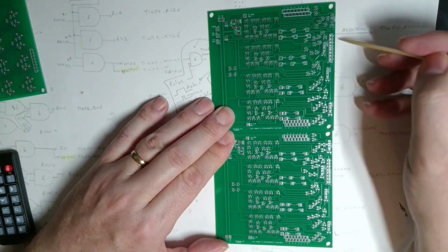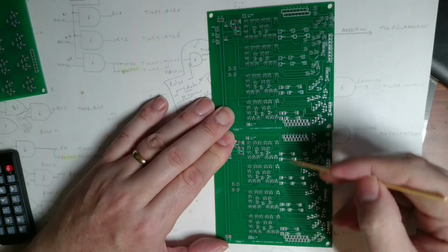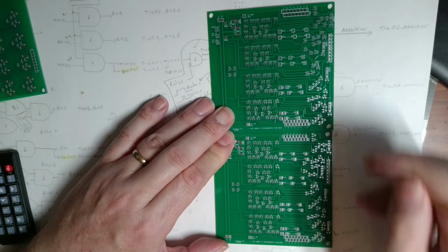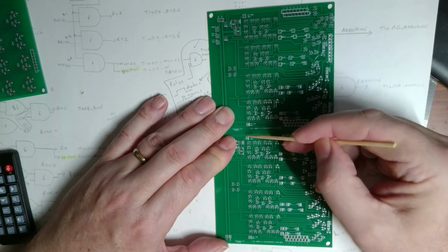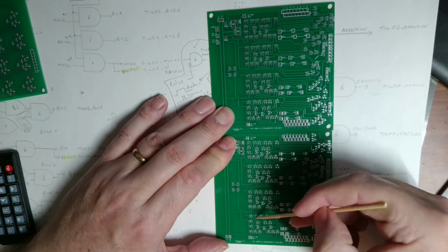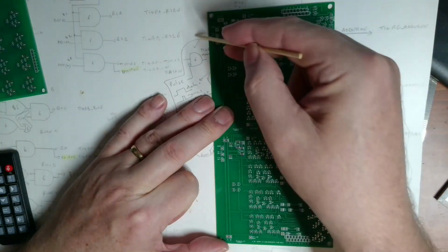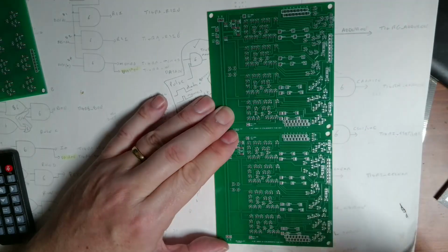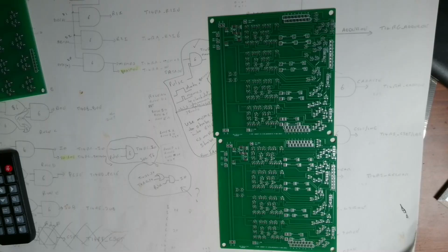So this would be, say, D0 to D3 coming out here, and this one would do D4 to D7 coming out here, and you just pick off which outputs you want onto your data bus. So the carry from this board will link across to here to carry on through these, and the output from this one doesn't come from here, comes from there, and the input comes up there, as you can see on the main board. So that's how the adder is.